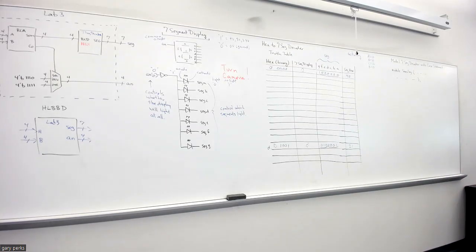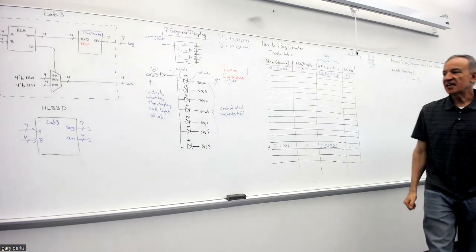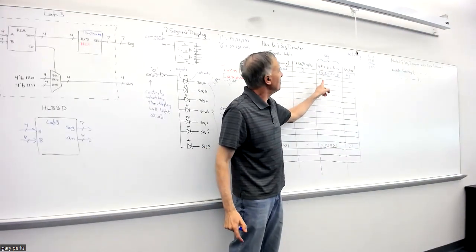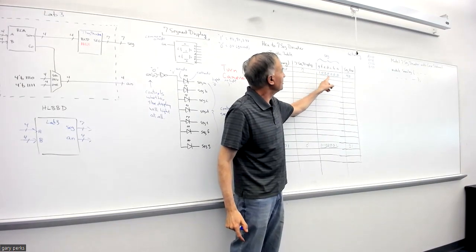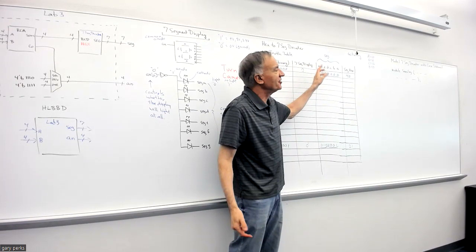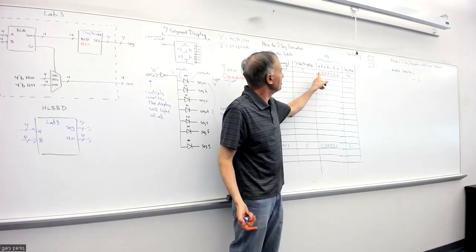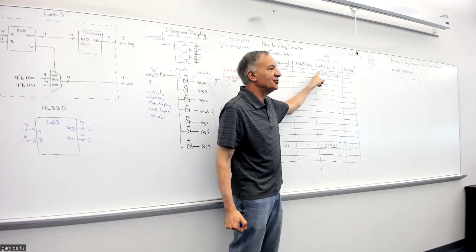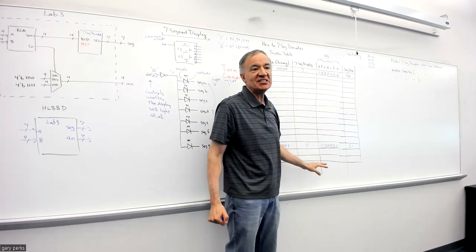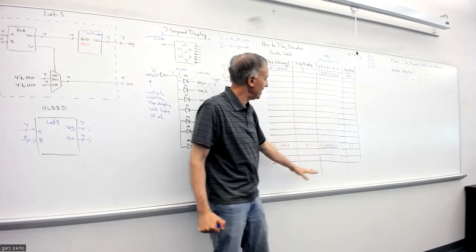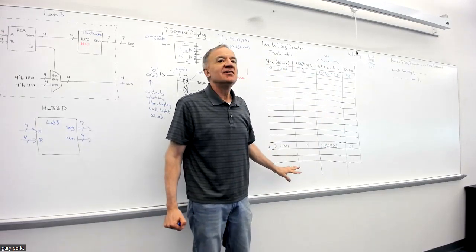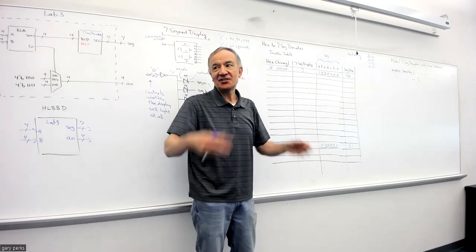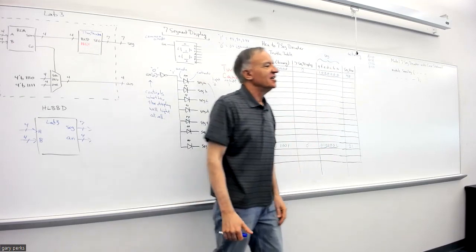in SystemVerilog. Because you could do this another way. You could come up with a truth table for all these outputs. When I say truth table, also K-map, right? If you wanted to get the reduced expression for all of these segment outputs, you could do it. You could have a K-map for G, a K-map for F. They would each be 16-cell K-maps, right? Because each output has 16 inputs. You could do that and then write out the Boolean expressions, like you did in the previous labs.